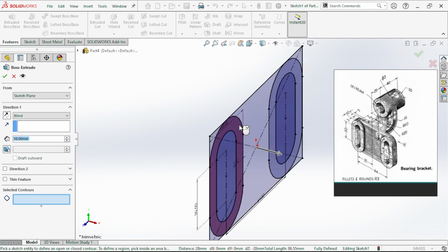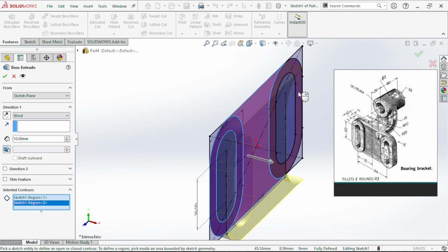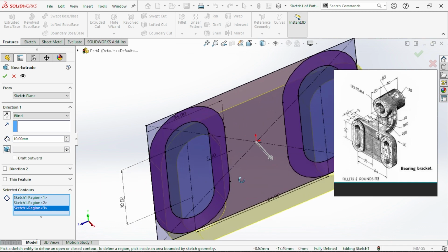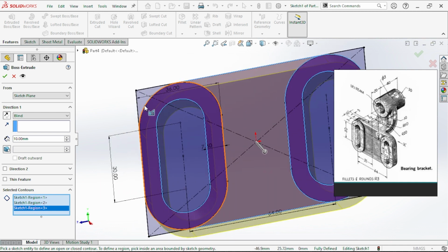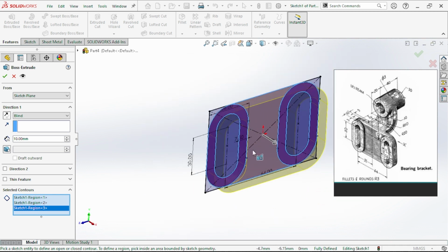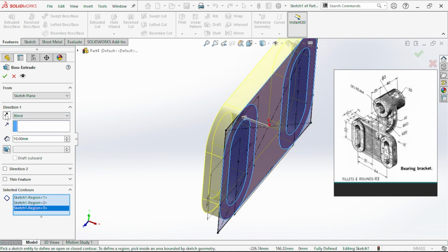Now carefully choose this slot, this section and this portion. If we just rotate over here, we don't choose this corner portion because the corner is rounded over here. So make it direction change. Click over here, make it the reverse direction, give this parameter 7 and press enter.